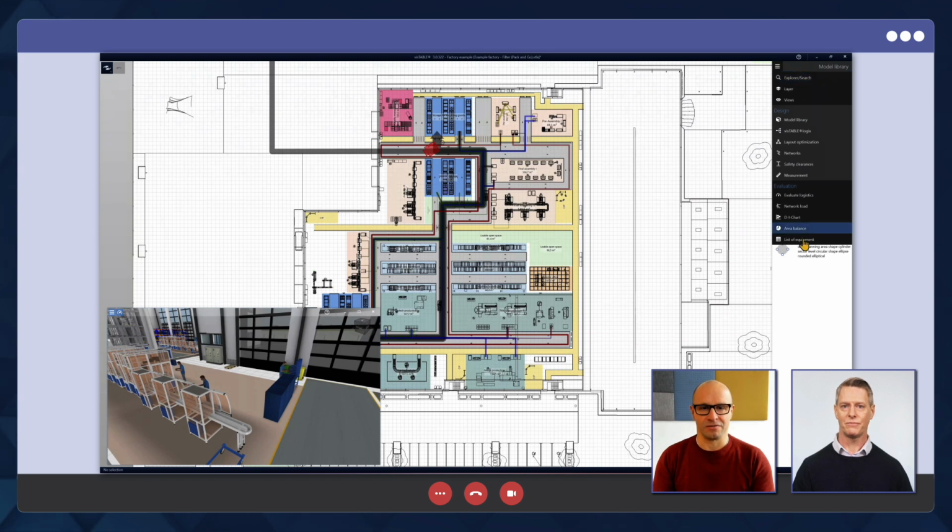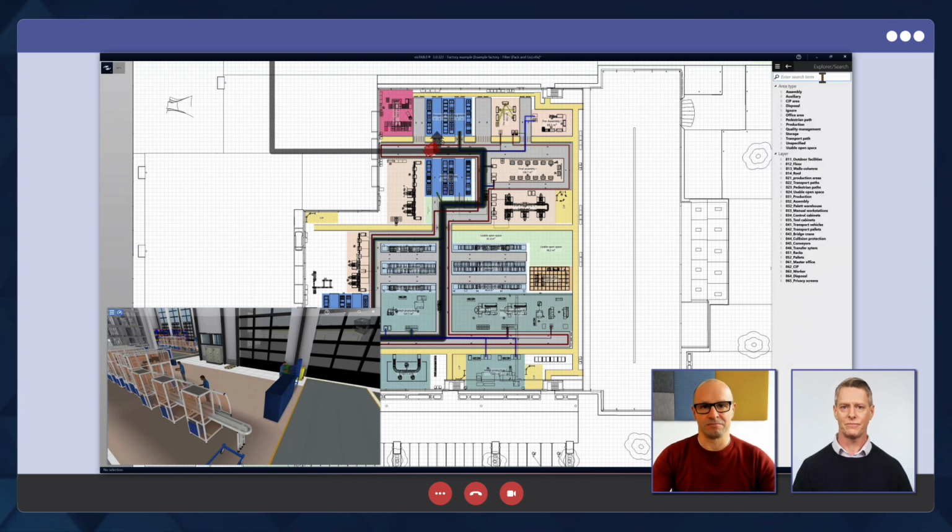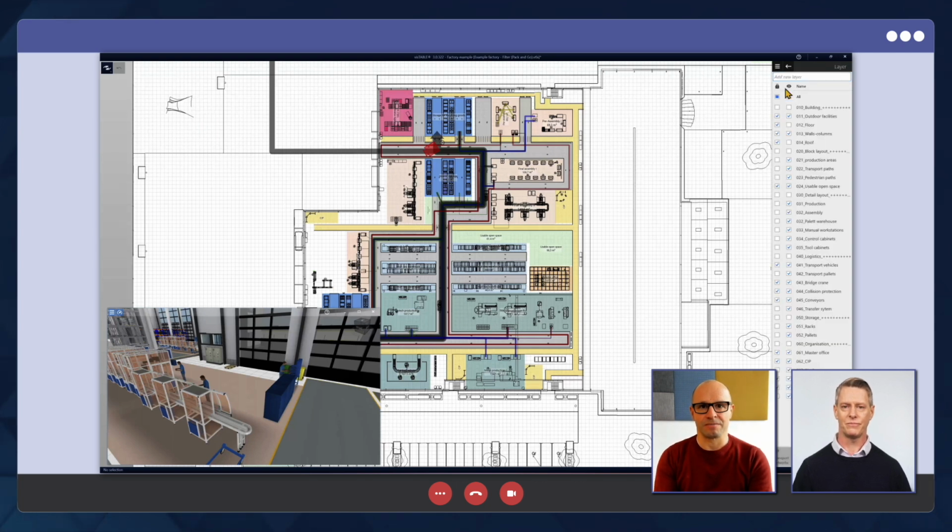Here on the right in visTABLE, we have divided these sections into 3 parts. There are a few general functions, then the creation functions, and the corresponding evaluation functions. You can easily find objects in the layout via Explorer search. Especially when the layout is larger, it is very helpful that you can either search for the objects by name, or that you search via the surface types here, or via the layers and filter out your objects accordingly.